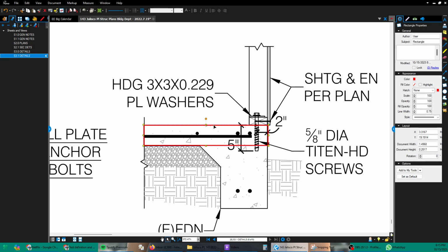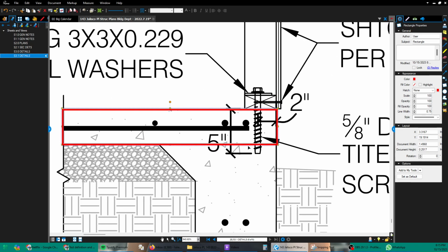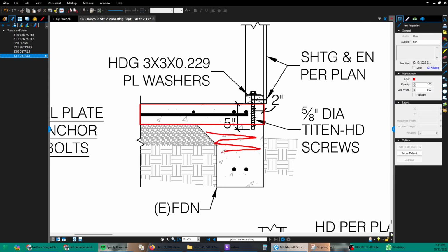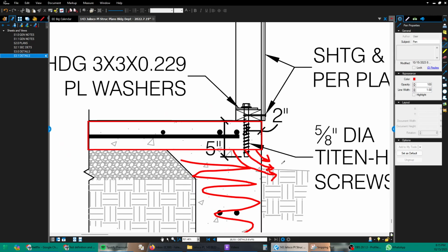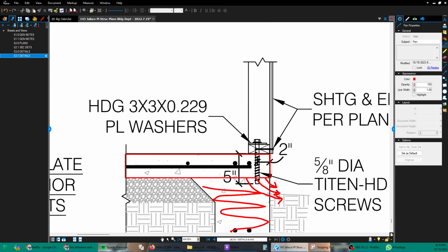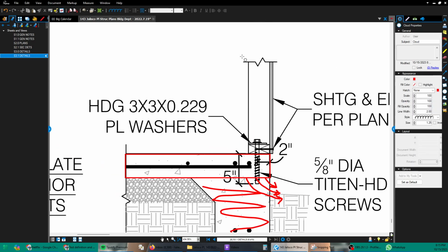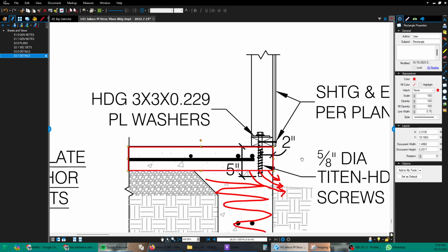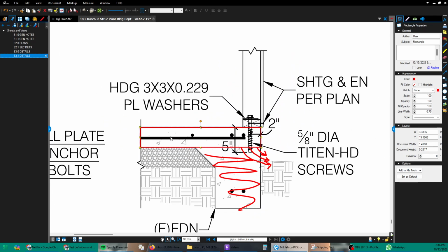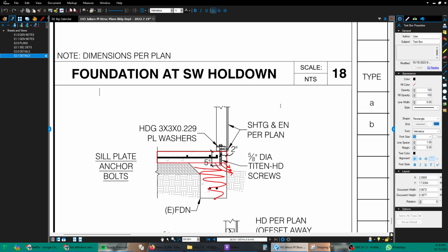And the reason, there are a few reasons. One is that if the concrete slab just looked like this and there were no thickened slab edge, then you can have this soil caving out. The soil that's right under this edge could start to cave out and get hollowed out, due to rainwater scouring under the edge of the slab. And that's going to cause the edge of the slab to become unsupported, and this wall above the slab is going to be sitting on the edge of a slab that is unsupported. So one reason for having a thickened slab edge, here I'll make a little list. Why have a thickened slab edge?